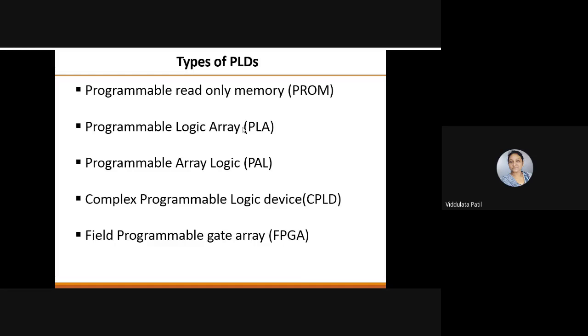One type is the programmable read-only memory, that is PROM, then the programmable logic array, that is PLA, and the programmable array logic, that is PAL. All these three are types of simple programmable logic devices, called SPLDs.